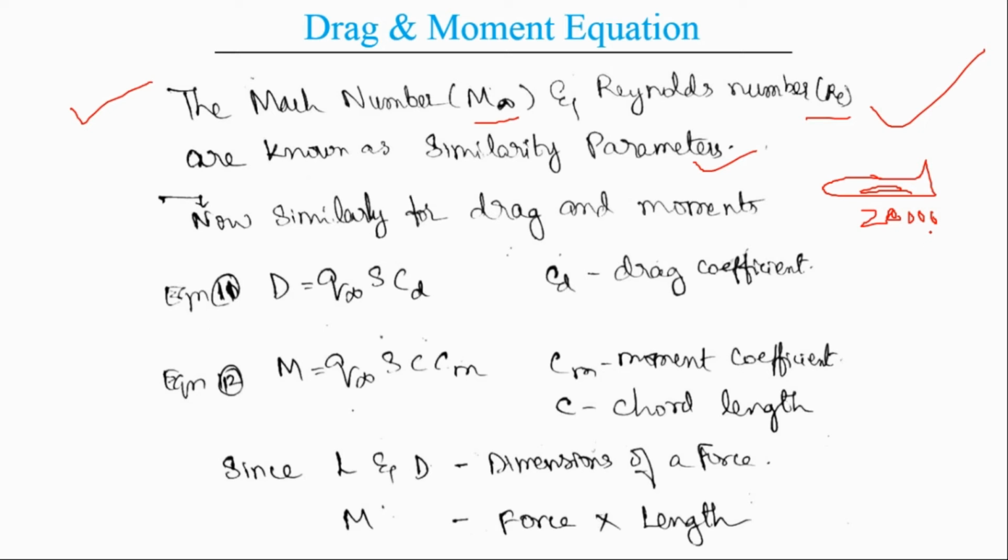But one other thing I can do is put that model in the wind tunnel and obtain the experimental and numerical values for it. How do we do that process in the wind tunnel? This is how we do that by using similarity parameters. We substitute the Mach number and the Reynolds number, and we match both of these conditions with the flight conditions at 20,000 meters altitude.